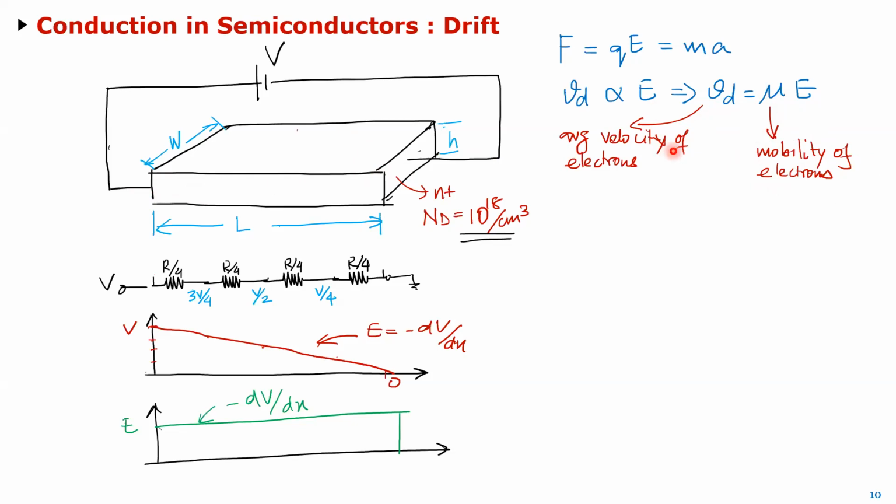So if you know that, the way to calculate current is, as I said, since this is a uniform material, I can calculate the current in any of these branches because KCL needs to be valid, right? So I can apply KCL here, or here, wherever it is. I can take any cross section here, and whatever current flows through that cross section is obviously the current flowing in the entire network, because KCL still needs to be valid, since there is no charge storage element here.